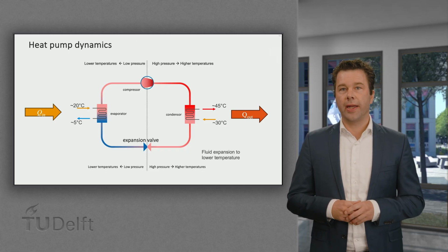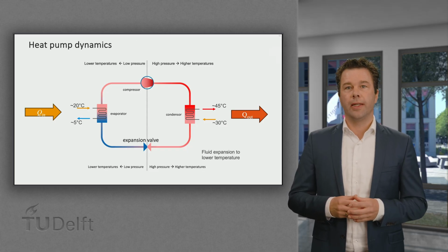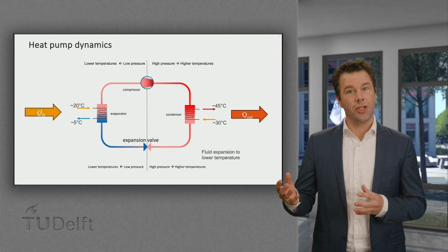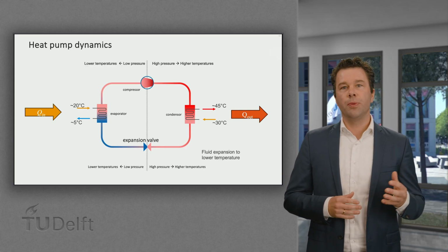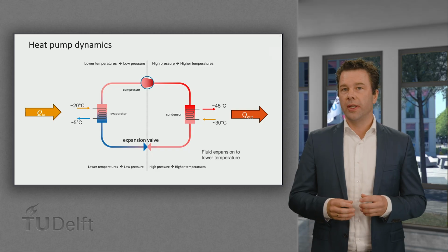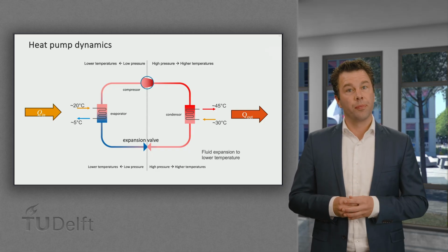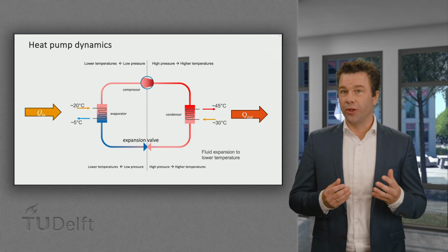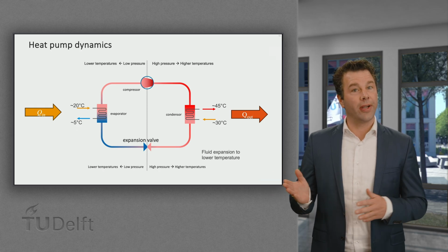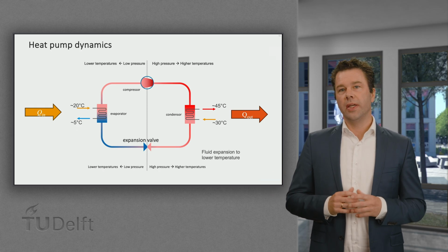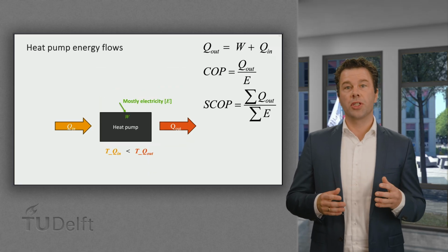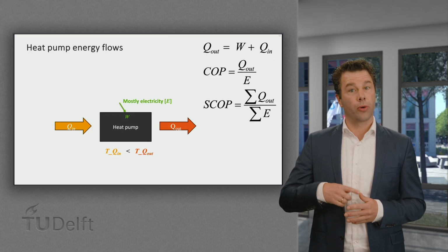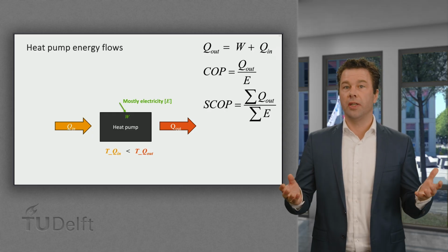Heat pump manufacturers design the composition of the working medium such that it evaporates and condenses at specific pressures and temperature levels corresponding to the required application of the heat pump. As we use environmental sources of heat as input, the available temperature may vary. Also, the heat demand in buildings or other heating processes vary. As a result, the temperature conditions both at the evaporator and the condenser vary over time. Therefore, you need to be aware that the momentary occurring COPs will vary, and assessing heat pump performance requires the integration of occurring COPs over time to calculate the average COP.